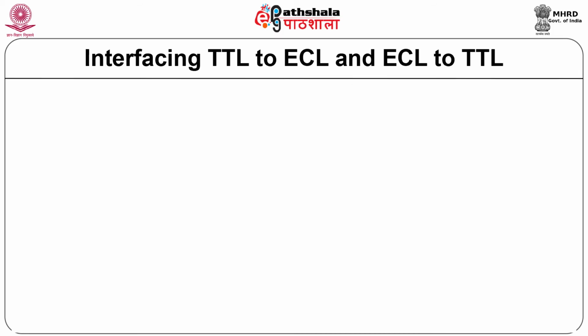Interfacing TTL to ECL and ECL to TTL. TTL to ECL and ECL to TTL interface connections are not as simple owing to the widely different power supply requirements of the two types. ECL devices have differential inputs and differential outputs. Special chips are available that can take care of all these aspects. These are known as level translators.